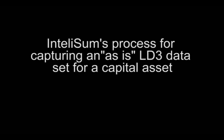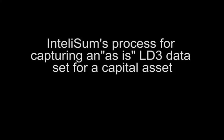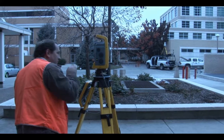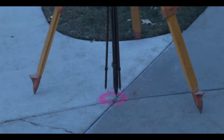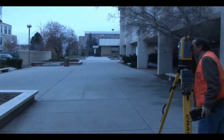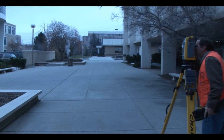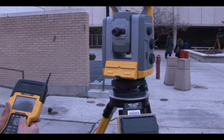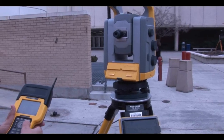Intelisum's process for capturing an as-is LD3 dataset for a capital asset. The process to capture an as-is life-dimensional 3D dataset for a capital asset combines two well-proven practices. First, the practice of dimensional survey control, and second, the practice of scanning the site with a high-density laser scanner. The dimensional survey control will be used to tie the scan data to a specific coordinate system. This process requires the following 9 steps.